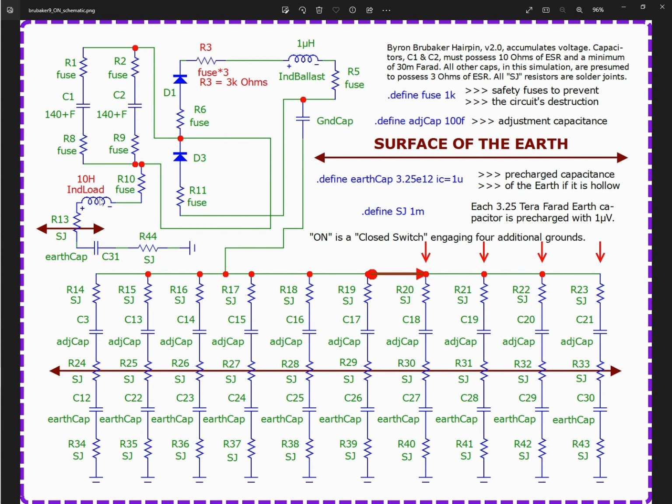So the ratio of voltage to current on the load has to be in the vicinity of a factor of 7. 7 times more voltage than current, which means your impedance is 7 ohms. Your reactive impedance, well, in this case, yeah, because it's a reactive component. So in order to get that suppressed down, instead of it climbing, which I didn't want it to do, I don't want voltage in excess of voltage on the load.